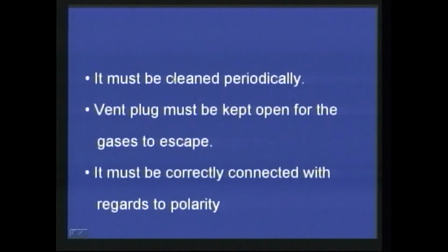It must be cleaned periodically. The vent plug must be kept open for the gases to escape. Also, it must be correctly connected with regard to polarity, otherwise it gets discharged.